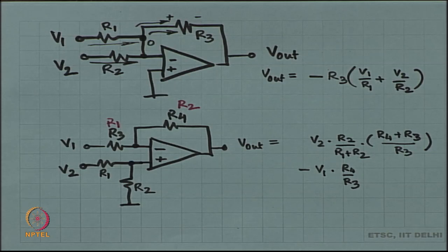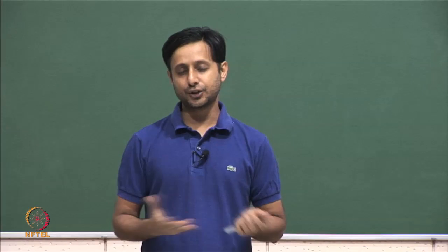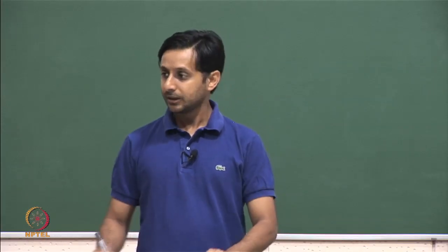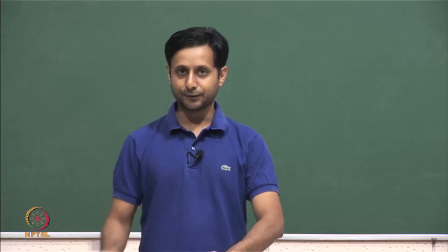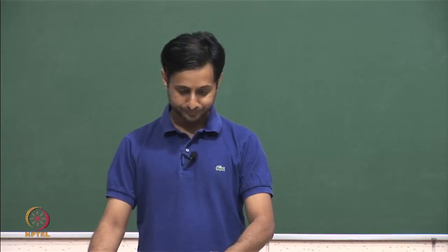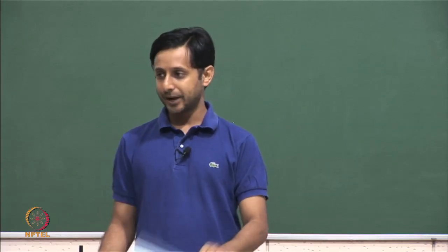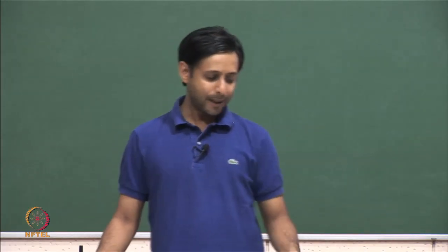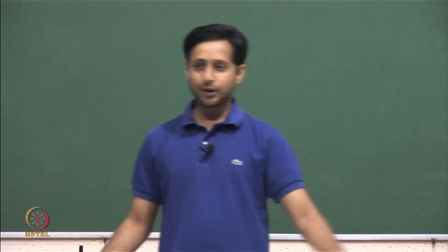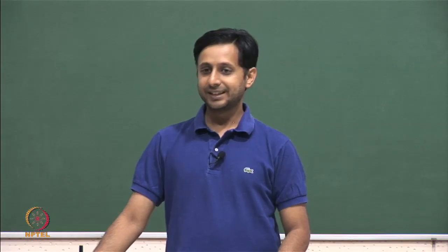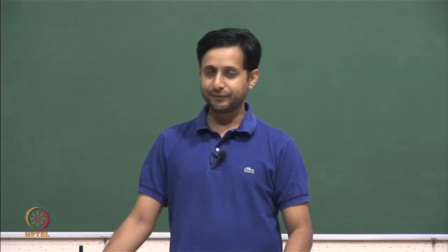You can figure out, you can instead of doing just an addition or just a subtraction, you can do a weighted addition, weighted subtraction by utilizing the values of R1, R2, R3, R4. Okay. So, this is just addition and subtraction operations. The op amp can also be used to do other more interesting operations, for example, integration and differentiation.